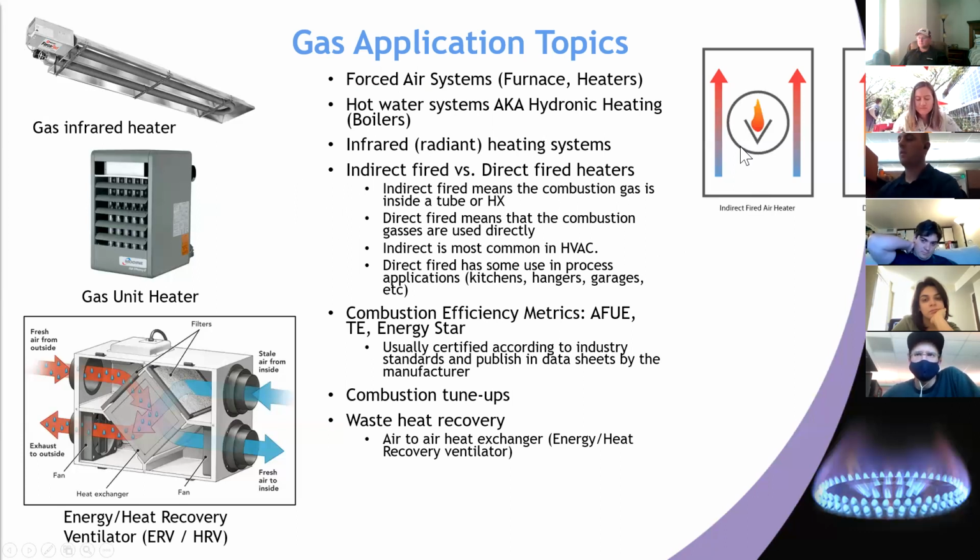In an indirect fired heater, the combustion gases from the burning are contained within a tube or a coil, and air or water is passing over that tube or coil to pick up the heat. So pretty much everything we'll see in most applications is going to be indirect fired. There are only a couple of applications where we would see a direct fired heating source.